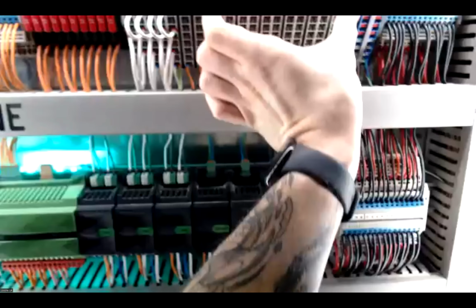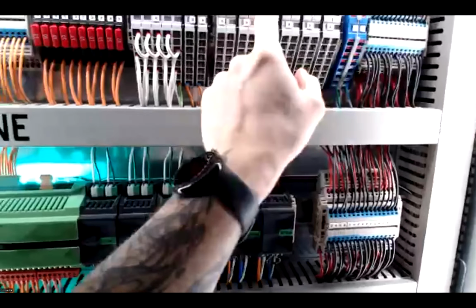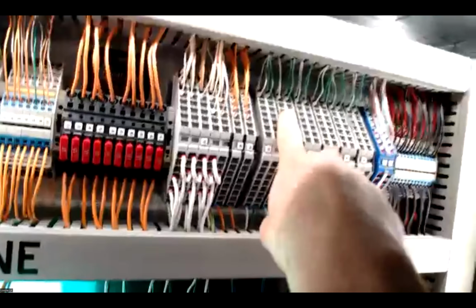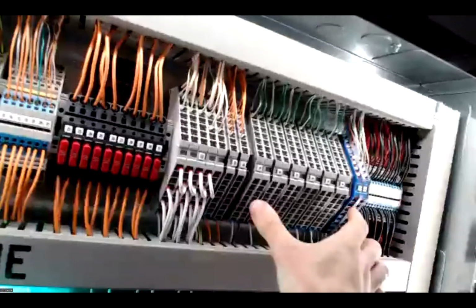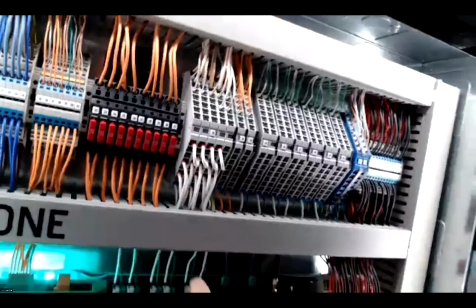We're going to remove the whole block of terminals, and instead of doing this, we can go directly on top of the tree extension, because the tree extension or the push-in connector already has 4 inputs. So because we only have 2 outgoing connections, we could have saved ourselves a bit of money and a bit of space in the panel, just going directly on top of the extensions.